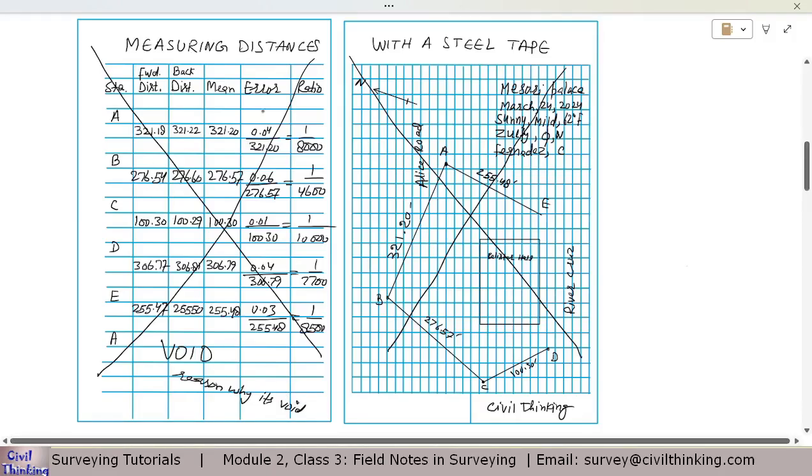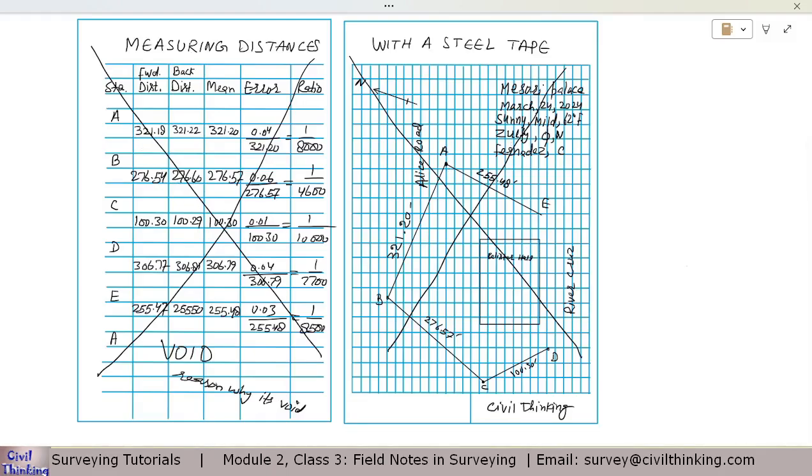You have to draw these diagonal lines. Again, never cut these papers and never throw them out. You have to keep everything in the field book, so there should be no paper cut. If there is a mistake, no problem, just draw these cross diagonal lines, because sometimes you might need this.